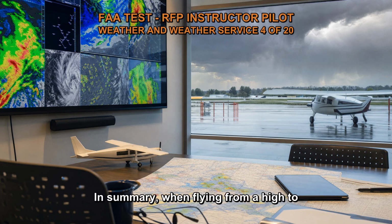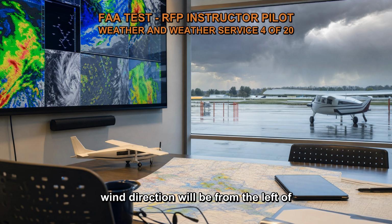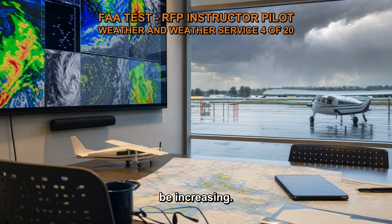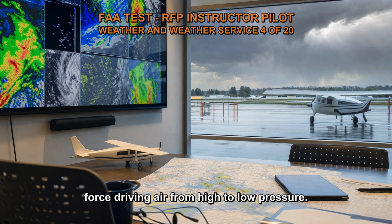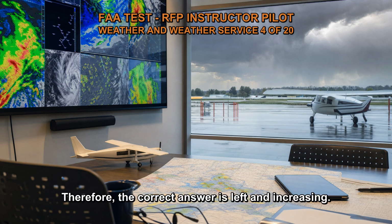In summary, when flying from a high to a low-pressure area in the Northern Hemisphere, the wind direction will be from the left of the pilot's heading, and the wind velocity will be increasing. This is due to the clockwise circulation in high-pressure systems and the counterclockwise circulation in low-pressure systems, as well as the pressure gradient force driving air from high to low pressure. Therefore, the correct answer is left and increasing.